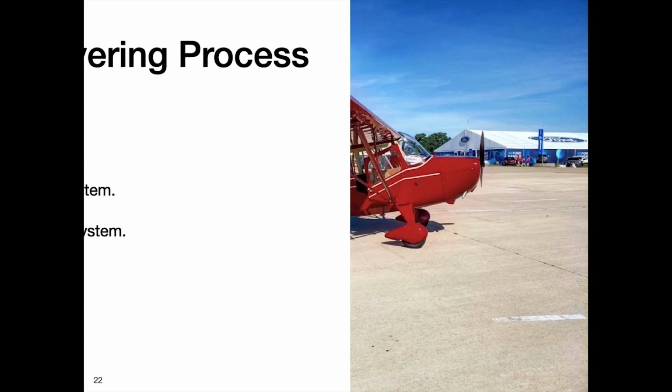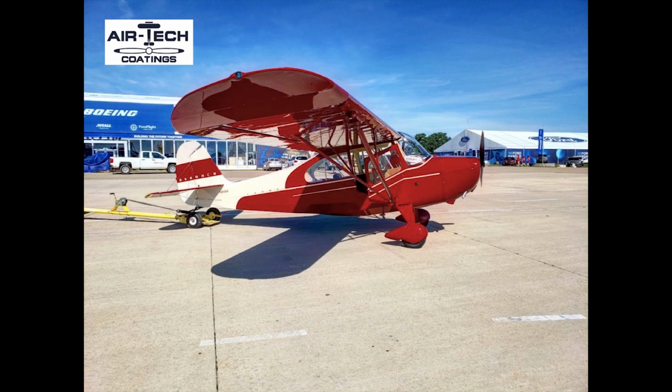First one is the AirTech covering system, also called AirTech coating, which is a company's solvent-based, non-automotive polyurethane fabric covering system. Both the primer or sealer and top coats have been formulated out of flexible based polyurethane just for aircraft use. This means that unlike automotive paints, there is no flex additive that needs to be added when mixing the primer or paint before spraying.